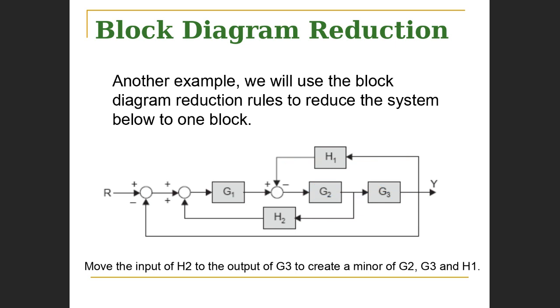The same thing can apply for the summing node. Let's say we choose to move the summing node. Move it where? We want to move it to a point where it simplifies the procedure. And in so doing, we could move the summing node from here to this point. So it would now be right here. Okay, so here you could do either one. You could move the pick-off point or you could move the summing node.